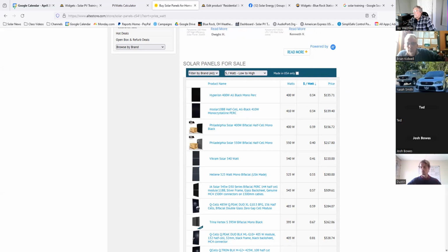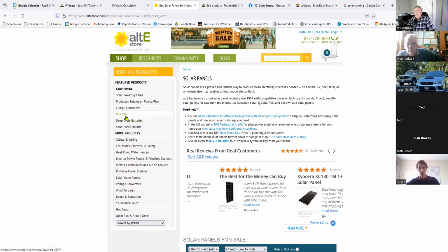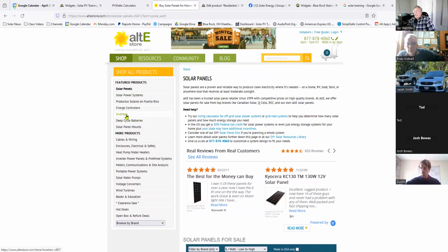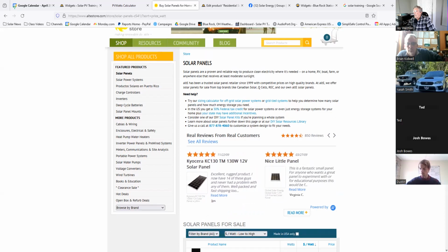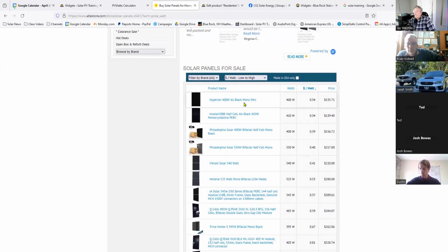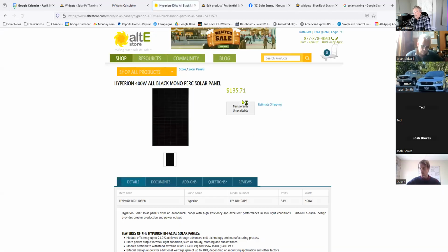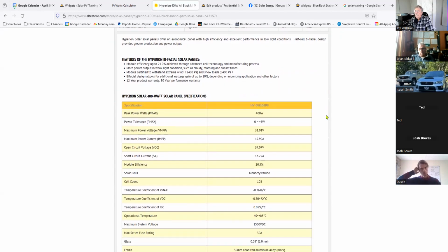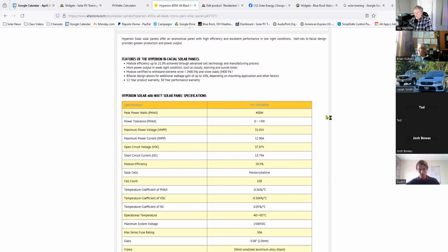So at this stage, now we got to look at buying an inverter. Before we move off of this panel, we've decided this is the panel we're going with. So I'm going to make a couple of notations as far as the system. I want to note down what is the ISC, what is the IMP. So here's the VMP is 31 volts.